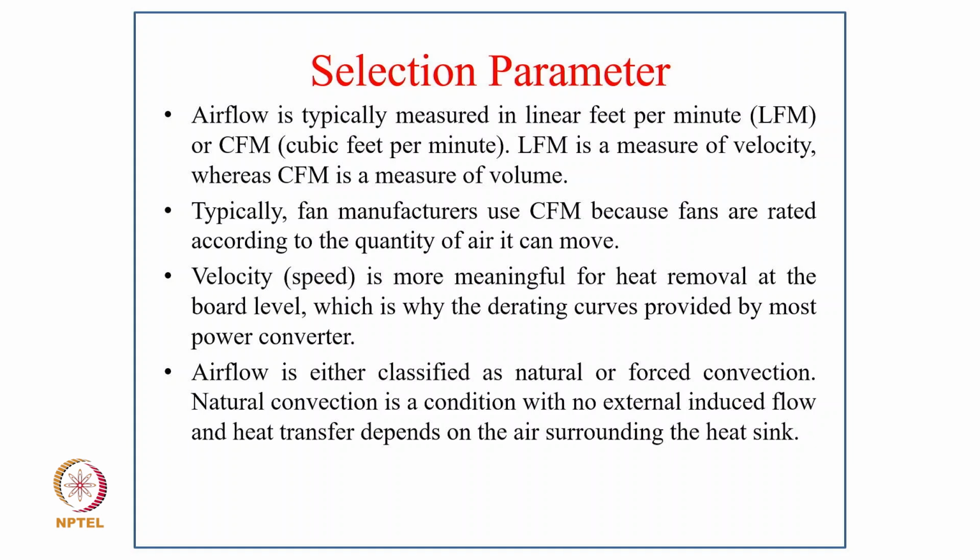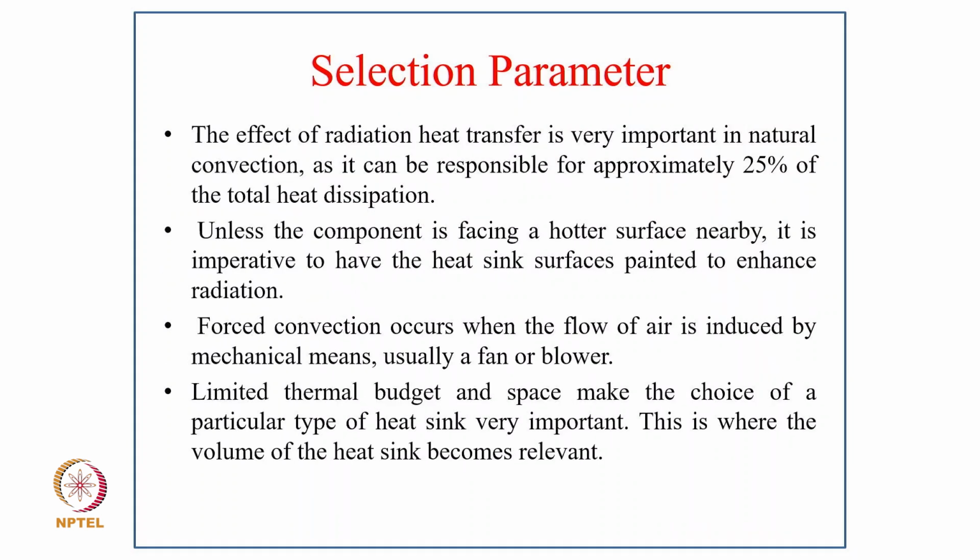Natural convection is a condition with no externally induced flow, and heat transfer depends on the air surrounding the heat sink. The effect of radiation heat transfer is very important in natural convection, as it can be responsible for approximately 25% of the total heat dissipation, and unless the component is facing a hotter surface nearby, it is imperative to have the heat sink surfaces painted to enhance radiation.